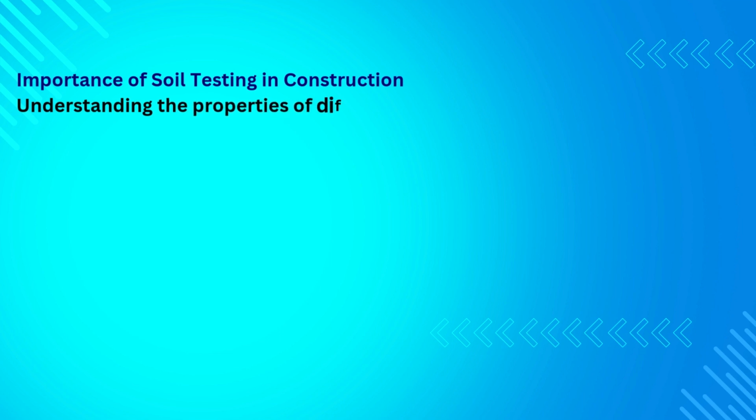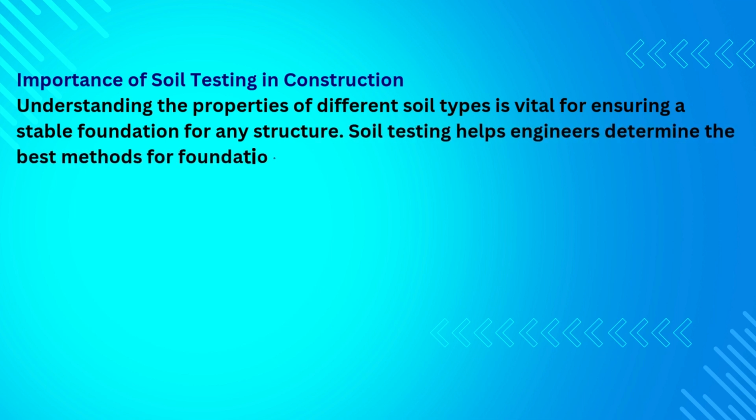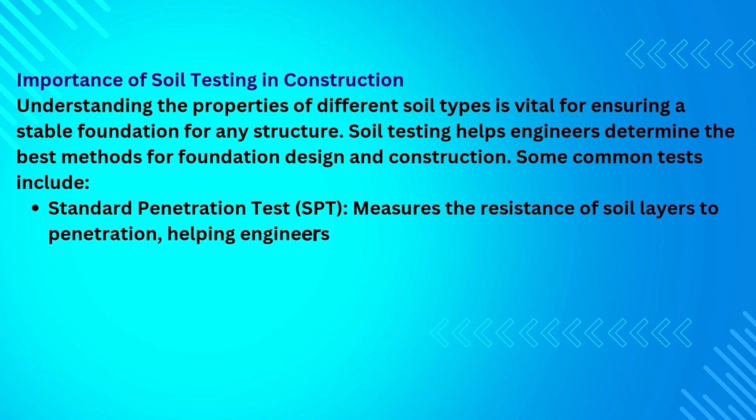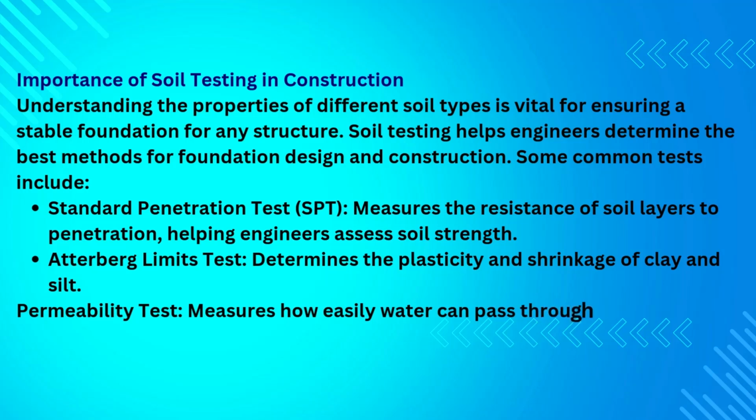Importance of soil testing in construction. Understanding the properties of different soil types is vital for ensuring a stable foundation for any structure. Soil testing helps engineers determine the best methods for foundation design and construction. Some common tests include: Standard Penetration Test. SPT measures the resistance of soil layers to penetration, helping engineers assess soil strength. Atterberg Limits Test determines the plasticity and shrinkage of clay and silt. Permeability Test measures how easily water can pass through soil, which affects drainage and stability.